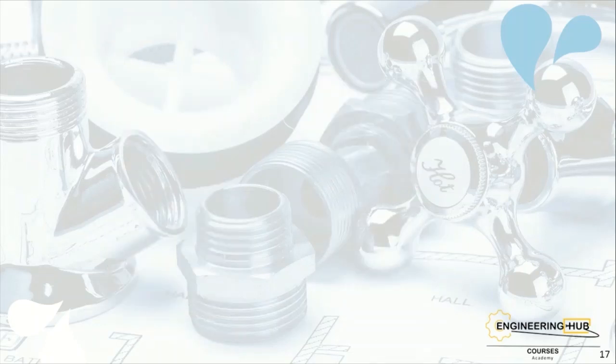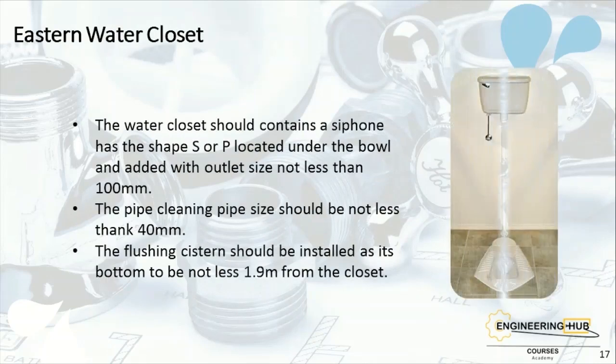Now we'll talk more deeply concerning the eastern water closet. The eastern water closet should be connected by a PVC pipe under the bowl, and it can be S or P type as we explained before, but its outlet size should be not less than 4 inches. The vertical pipe which takes charge of the bowl cleaning should have a diameter of not less than 40 mm. The preferred cistern type for the eastern water closet is the high-level cistern, installed with a minimum distance of 1.9 meters from the water closet.